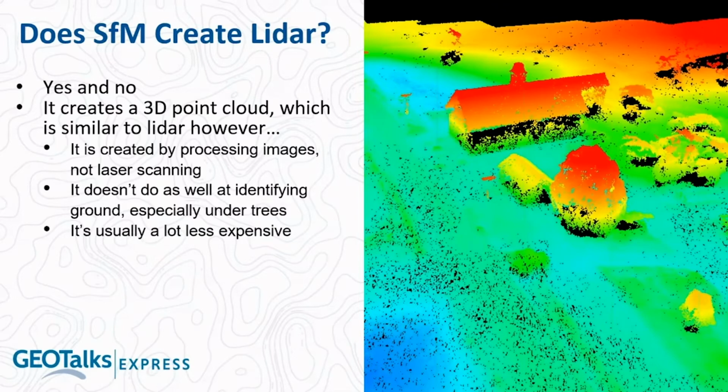Overall, capturing images with a drone is less expensive than capturing true LiDAR data. Most drones have the ability to easily carry a light camera. A lot of them come with a camera. You can easily capture pretty high quality images, whereas to collect true LiDAR data with that active method, you may need a bigger drone to carry a bigger, heavier, more expensive LiDAR sensor.